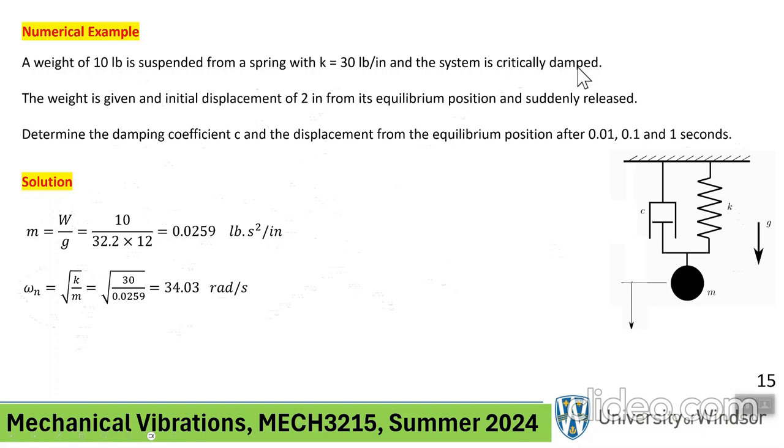But at the critically damped condition, critically damped condition means zeta is equal to 1. So you write the expression for zeta this way, either this or that. And because of what I did, omega n I have, m I have, zeta is equal to 1, and you're going to get your value of C.